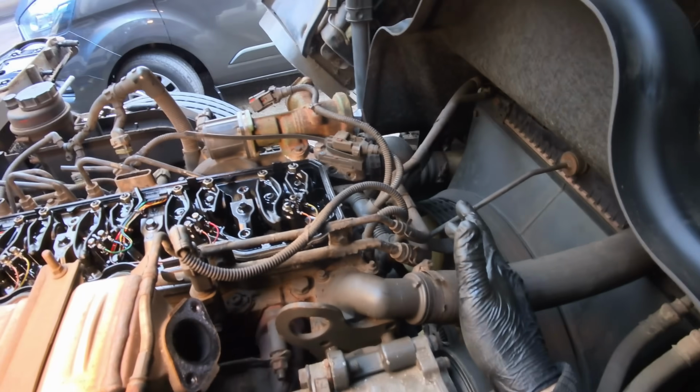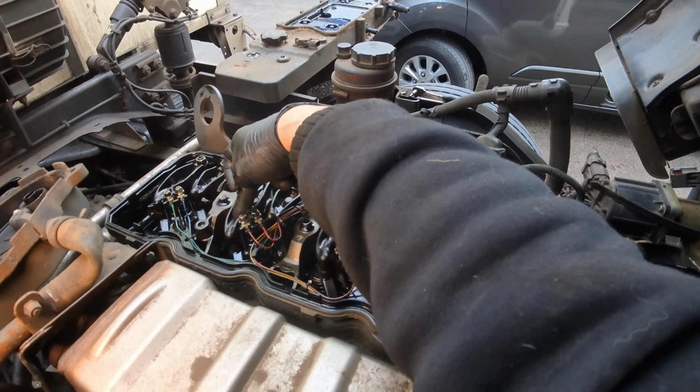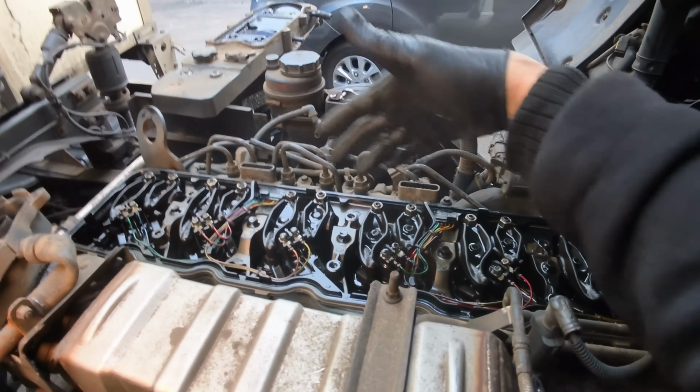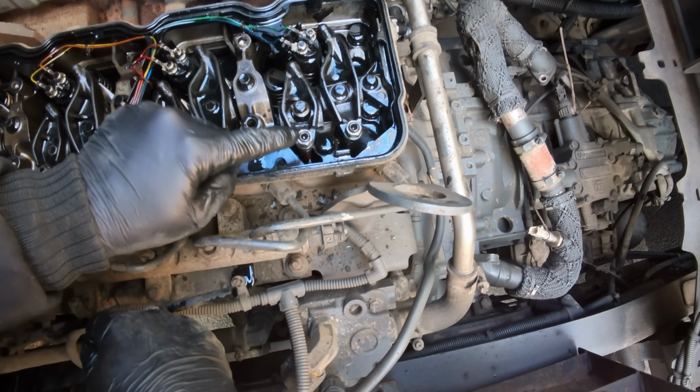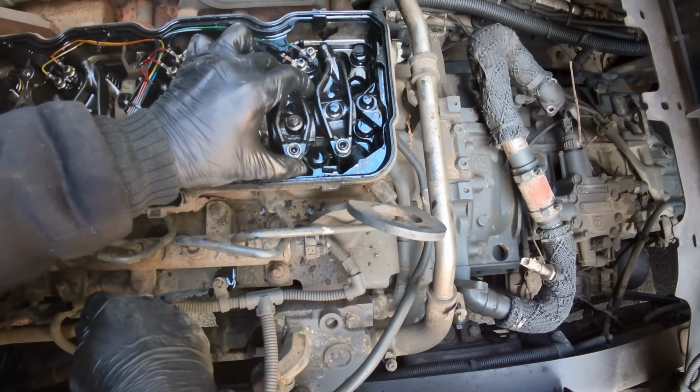What can be harder than finding TDC on an LF? Finding TDC on a CF with an LF engine in. So I've just got this over to TDC now. So that's TDC at the front. Exhaust rocker lever's on its way down here now, which means we're good to set this particular 360 stroke, but we're not. We're just going to set number 6 here. So we'll go and get some feeler blades. Now I've just had to wind this quite far down to get it to meet the clearance tolerances. So I'm just going to whip this out because I think this push rod might be bent.